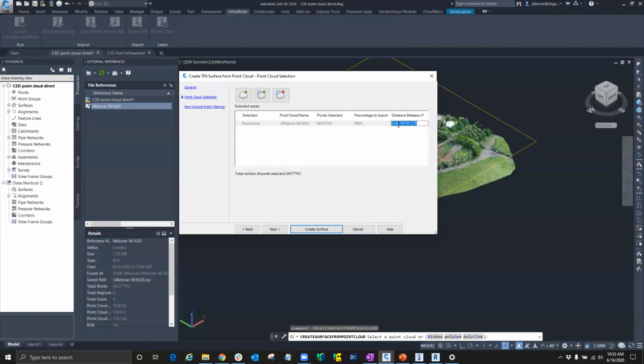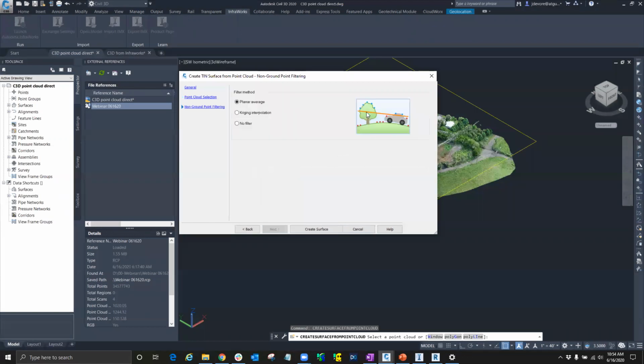So this is down past the thousands. Even if we went down to a 1/10, we can see it's down to 34, or even if we did a foot in between, or even 5 foot between, depending on what we're doing. Now, if we did 5 feet, we're down to 84,000 points that we're asking Civil 3D to do, okay? And then it also had, like I mentioned earlier,